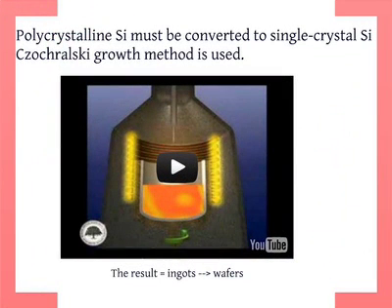Okay? Then there's a very important process which was developed by a Polish chemist named Czochralski, which produces the crystal from a molten melt. Essentially, you take a very small, very pure crystal of silicon, which you can create by chemical methods, since small crystals can be made. Then you use that as a seed crystal in molten silicon, so very, very hot silicon. You put the seed crystal in and very slowly pull it out.